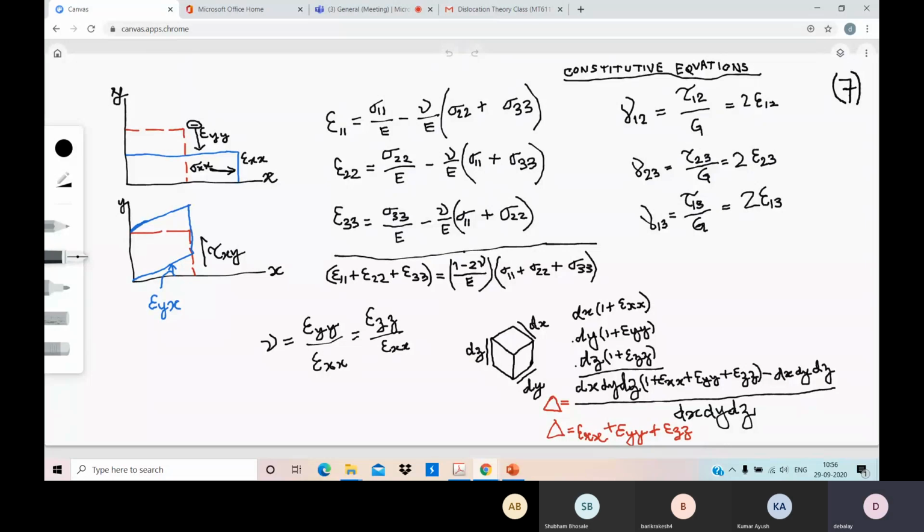Because we said that we cannot directly know what the stress is until and unless we see the strain. What we measure is the strain. So you do measurement of strain and you can calculate the stress tensor, and from that you can check the yield criteria and other things. So all are related, and to understand that relation, you first again look into this plot, xy axis, where the red dotted line is my initial body, on which I am applying a stress.